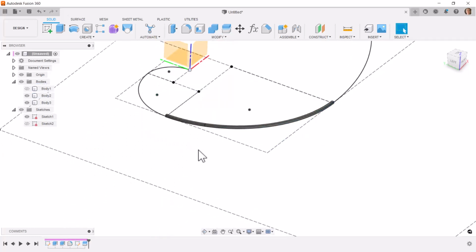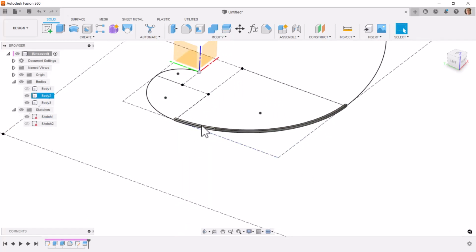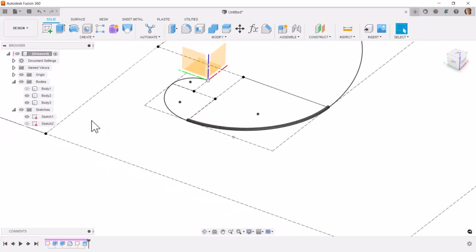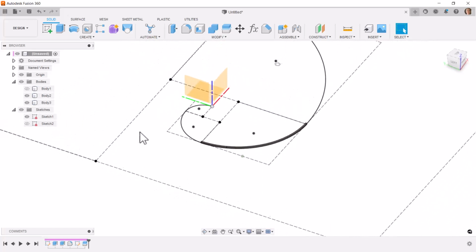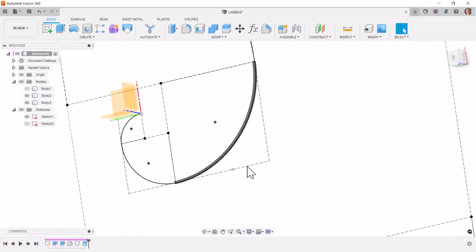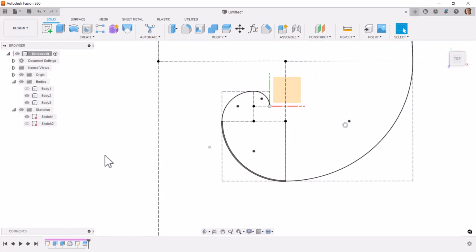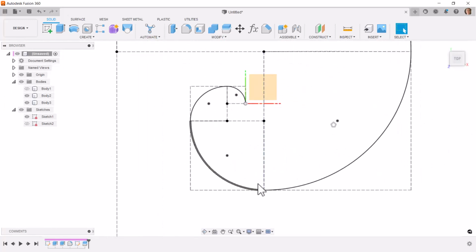I'll say okay to that, and so now this is two bodies, so this is a body and this is a body. Maybe split it that equal distance a couple more times, and then I'll have each one of these bodies that I can 3D print, and then glue them together after I get all of my bodies created. So that portion of it will be a bit manual. Maybe somebody clever can come up with a way to automate that as well.